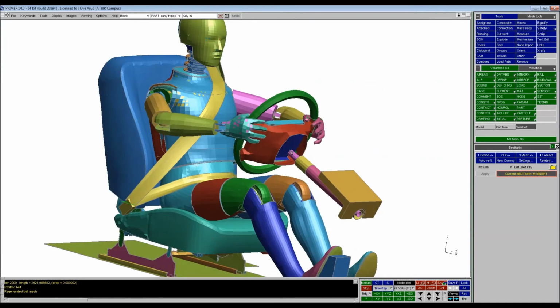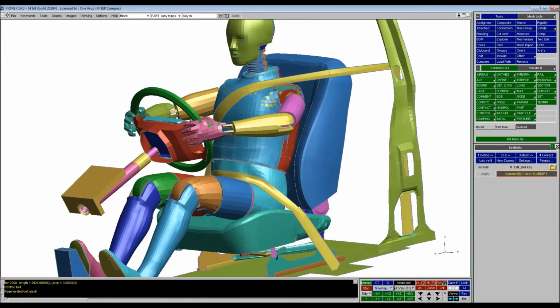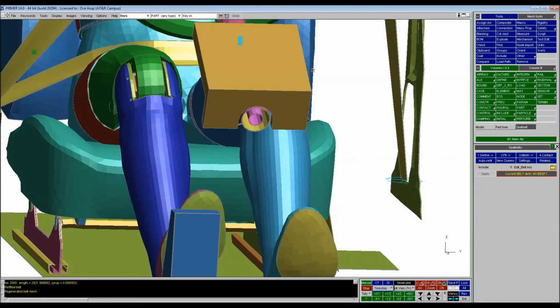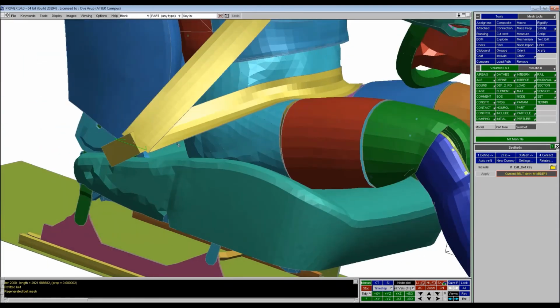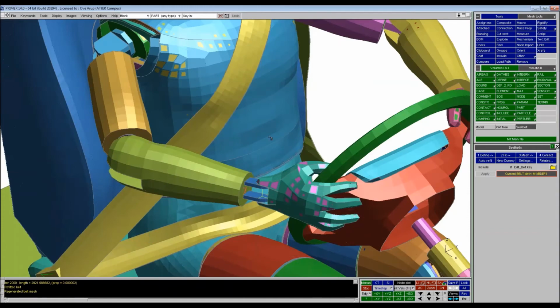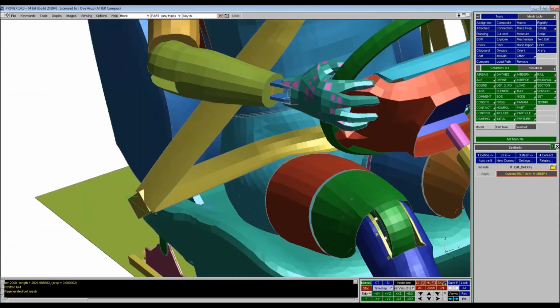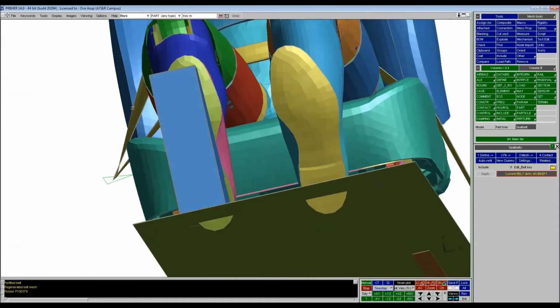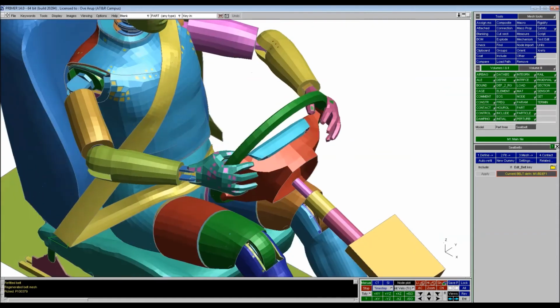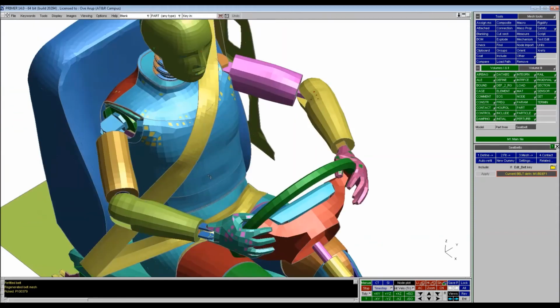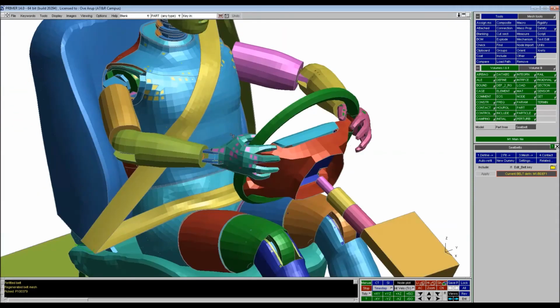It's always worth, whenever you do any of these refitting or auto refitting operations, that you inspect your belt. So we're looking for any crossed edges, any penetrations, because the buckle's okay, that wasn't in the definition to start with, but we're really looking for crossed edges on the chest or between the belt itself, belt to belt issues. But in this particular example, Primer's done a nice job of it, so there's no need for me to do any additional tweaking. If I needed to tweak it, then I would have done so using the same options as we used to create it originally.